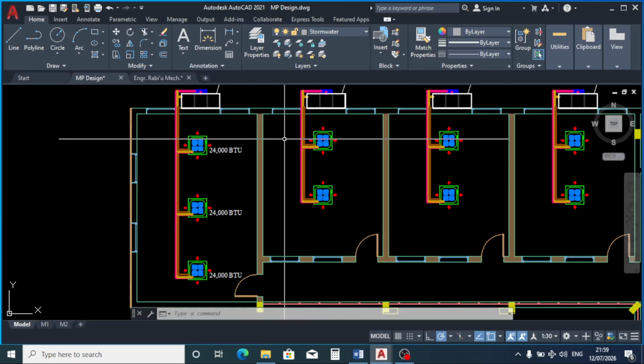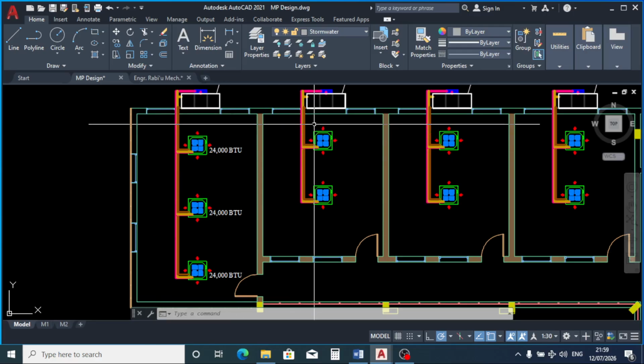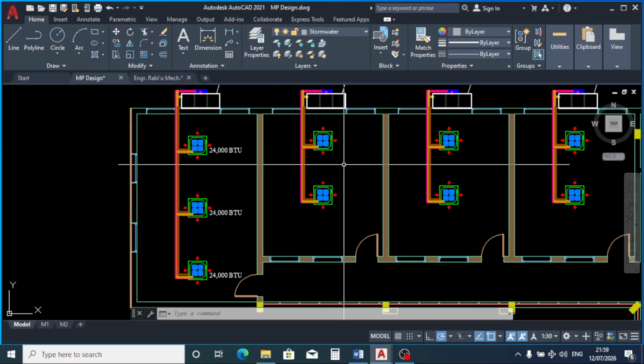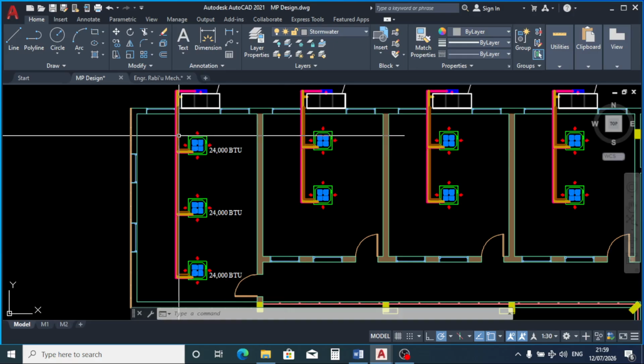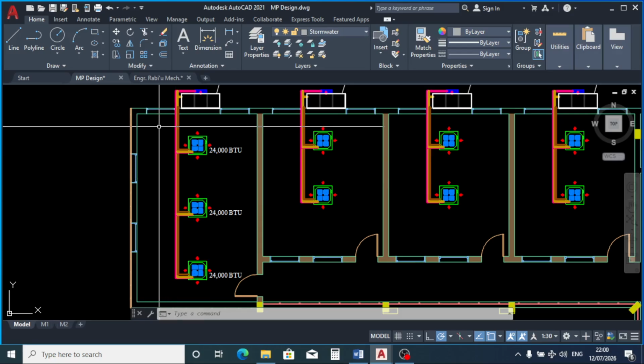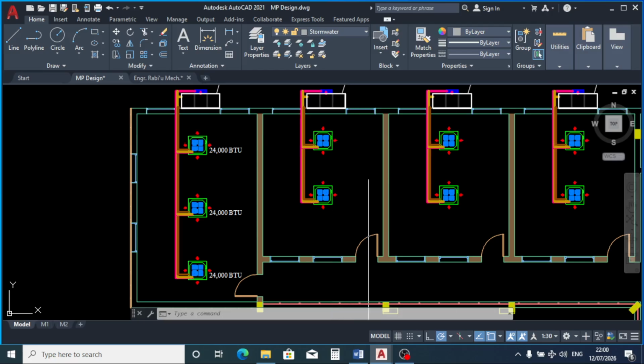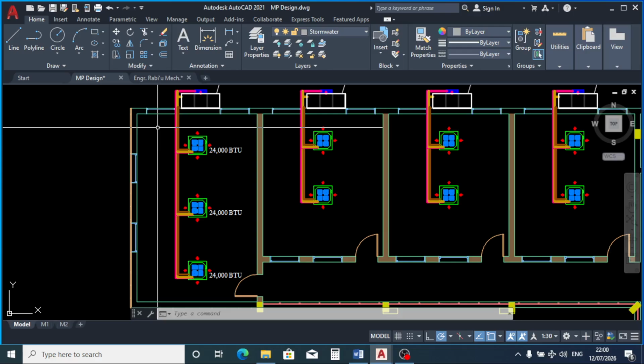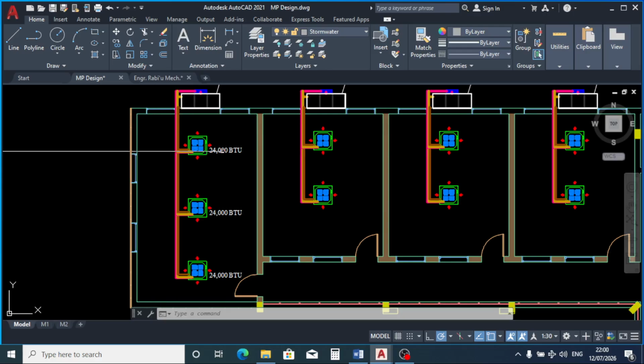You can choose to use the standard formula we used for this conference room and do the calculation all over, or you can choose to use a rule of thumb, which is a kind of shortcut. Since we have a pilot work, we can use the value for this conference room to make an estimate to get the cooling load for these spaces. So now, using the rule of thumb, recall the floor area for this conference room is